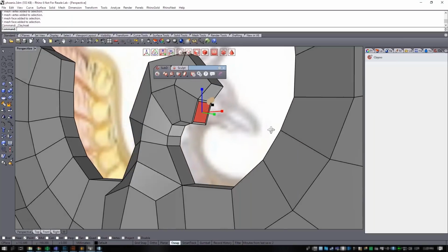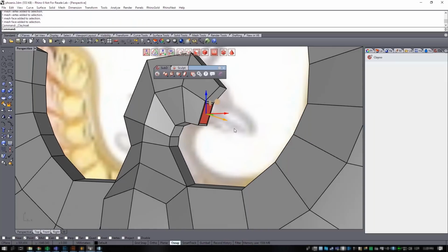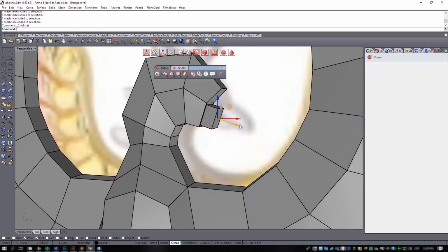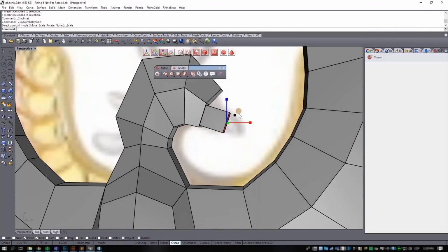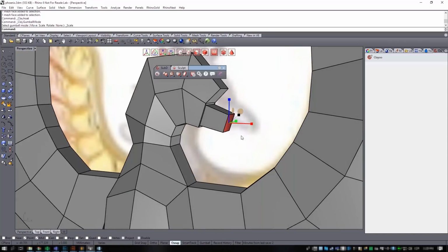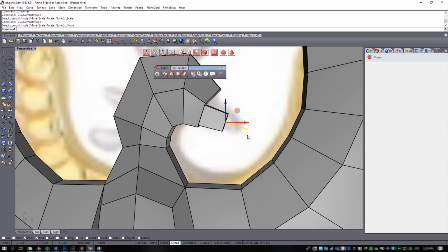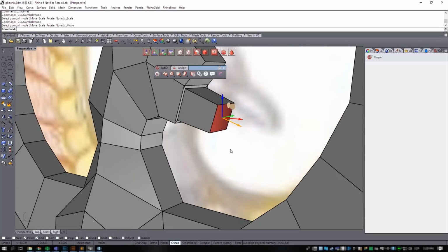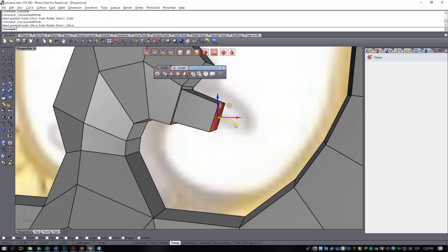Okay. And right now with the move gumball, I will extrude that, the same that we did before with the planar, right now we're going to do it with the 3D shape. So holding Alt and drag it a little bit. We can hold R to reduce the size slightly, and again W to move, using this orange arrow, it's for the normal direction, the direction where the face is pointing.